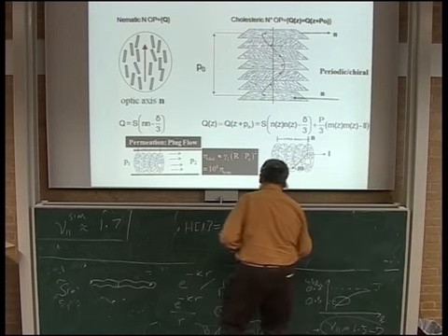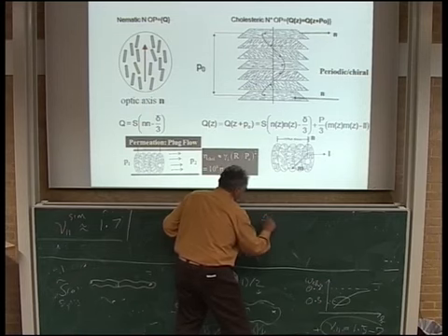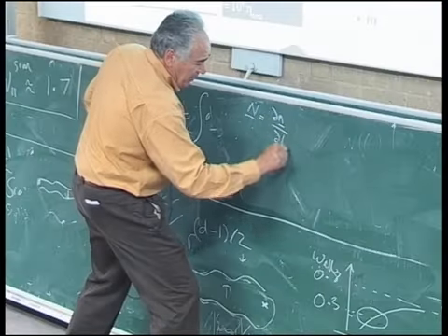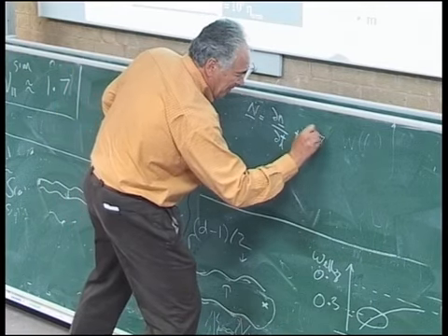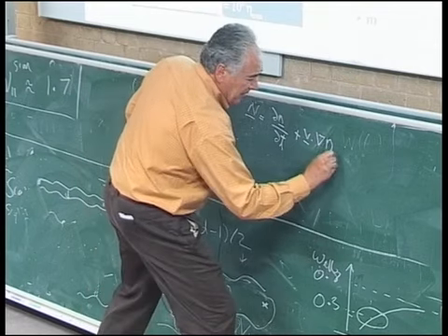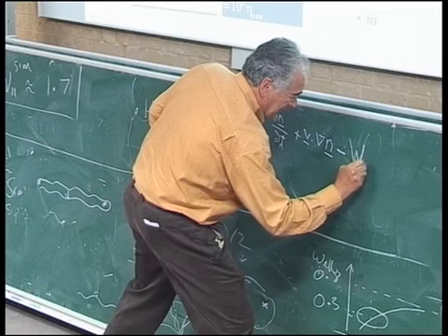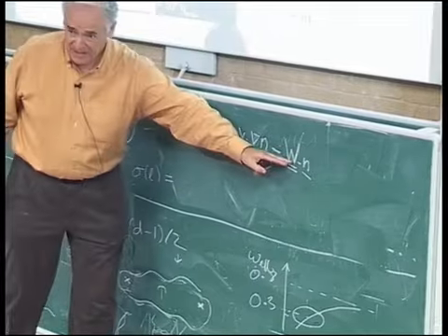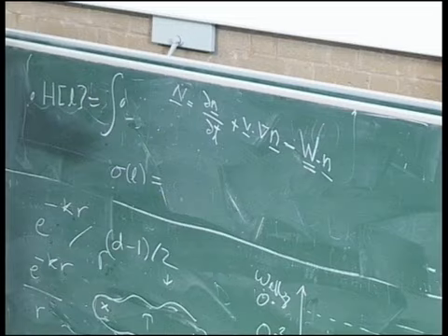So the key component in terms of dissipation or stress, viscous stress, is something called the corotational derivative for a vector type of model that looks like this. The last term is the spin tensor, the asymmetric part of the velocity gradient.